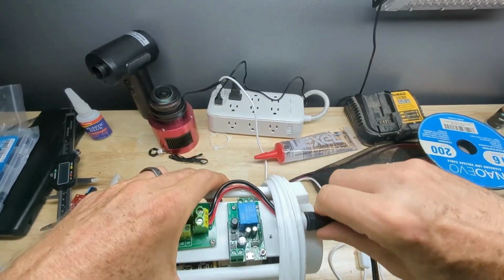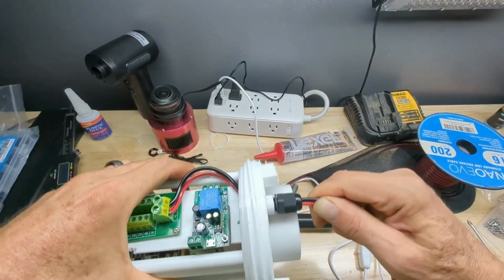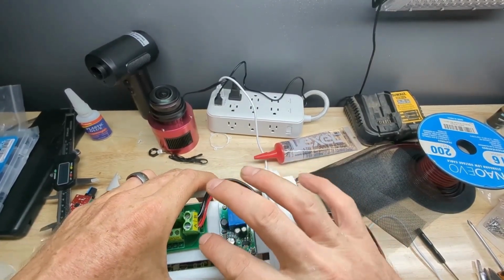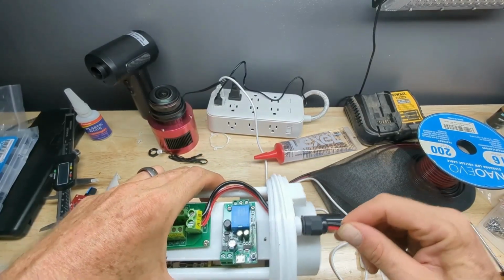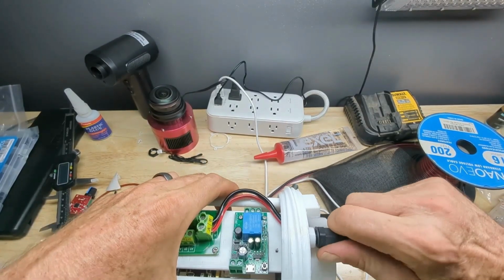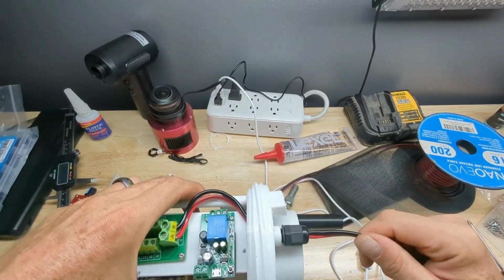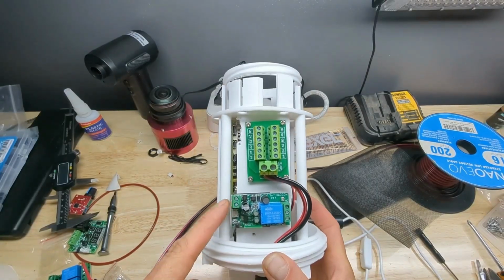you'll be very hard pressed. You will definitely have to really be trying to get this to actually pull out and potentially separate from up in here. And I do have a little gap on that cable. I need to get that pushed up in there just a little bit tighter, but you definitely want to make sure this cable gland is tightened so there's absolutely no way this cable can accidentally get tugged and yanked out. So we'll go ahead, and next step, we're going to wire this in.